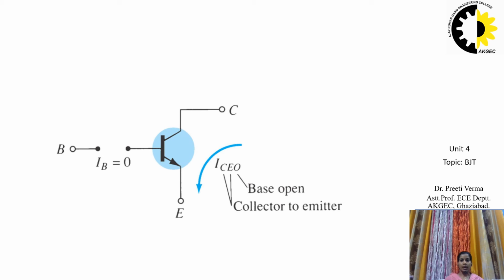When employed as a switch in the logic circuitry of a computer, a transistor will have 2 points of operation of interest, one in the cutoff and one in the saturation region. The cutoff condition should ideally be IC equal to 0 milliampere for the chosen value of VCE.